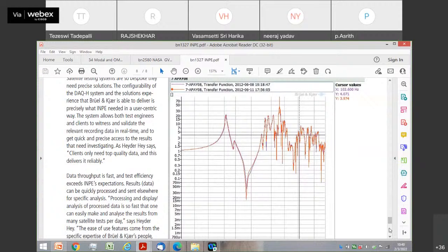So if you are saying loss of data, you would have to look at either the sensor or the data acquisition system to see where the loss of data could have occurred. I want to know, is it due to some phenomenon, or is it a sensor problem? One of the ways to check it out is to use a field calibrator and check the sensor with cable before doing the test.